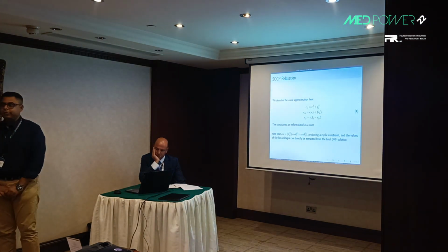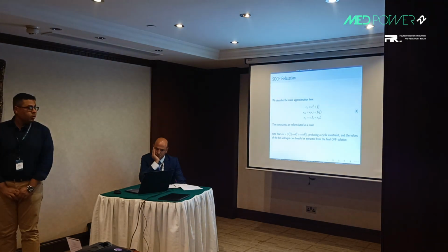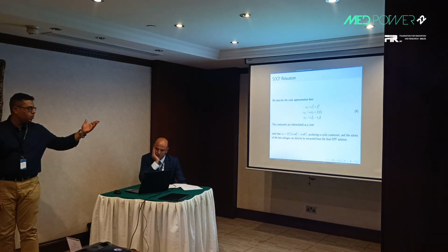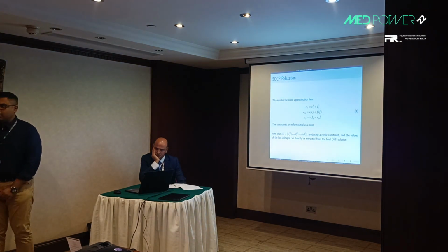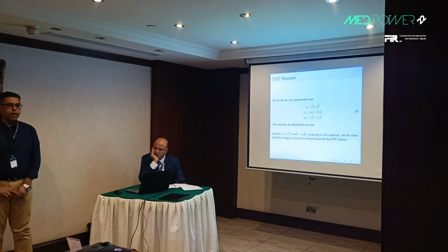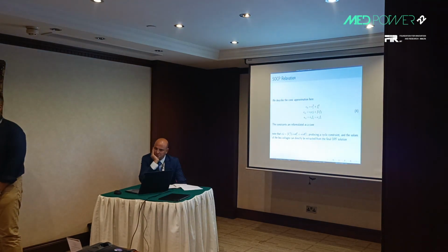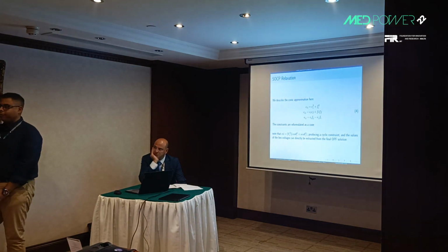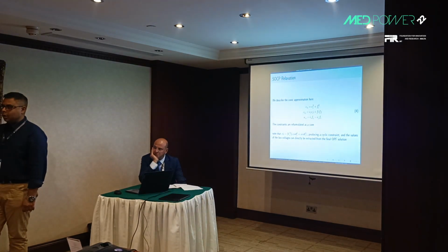So we lift the constraints further up. We use conic terms. This is basically the conic relaxation of the OPF, in which we make an equation of a circle. If you see the variables Cii, Cij and Sij, these are becoming an equation of a circle. So if we see from a point in a subspace, we see a cone.